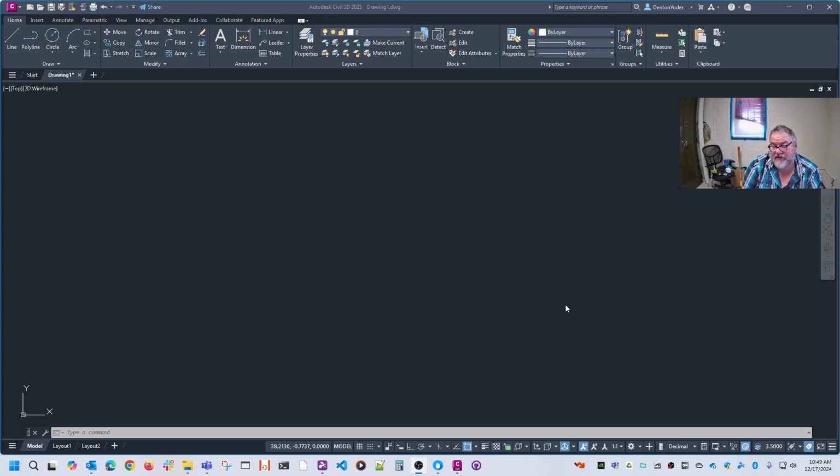We can put intelligence on that manhole by doing either a visible or an invisible attribute definition. DDATTE, Dynamic Dialog Attribute, is the editor. Attribute define, I think that's it. Anyway, when you define an attribute, what you'll get is a visible or an invisible piece of data.